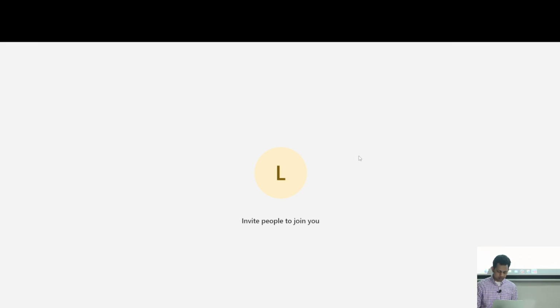So according to this Skydio website, what they claim, and we haven't verified this, is if we get a GSD of 12, then we can get an accuracy of about 36. So 0.36, 3.6 centimeters. Yeah, but again, that's with that camera and drone, so it may vary.